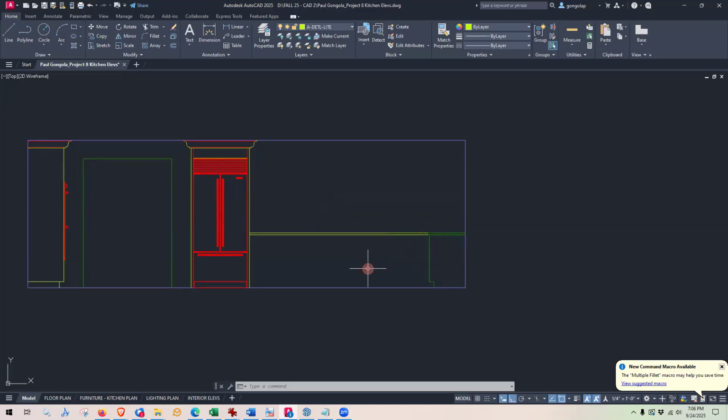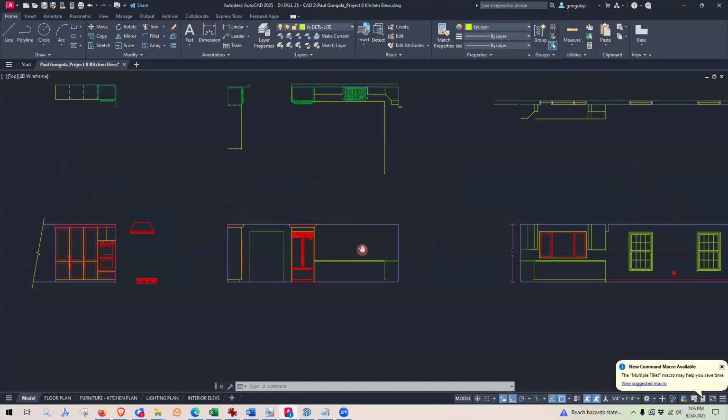This is pushed a little further back. Things that protrude way out are going to be on a heavier line weight, or major holes in the walls, like a window or this opening here, I'll use a heavier line weight for that as well. Okay, good.